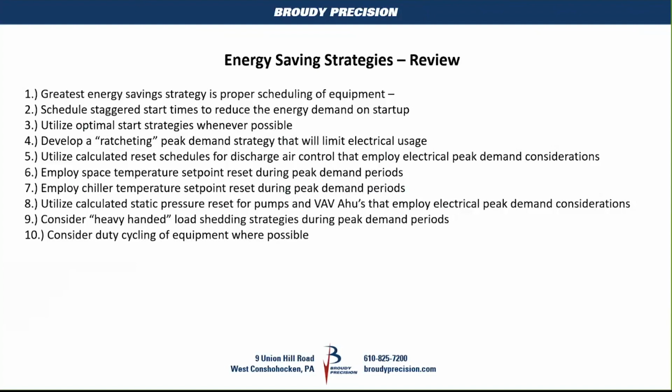We may start it up at 6, but the people don't get there till 8. If I'm only a degree out, optimal start says maybe I start up at 7:35 or 7:45, because I only need 15 minutes to get that 1 degree back when the people get there at 8. That's what optimal start does, and it saves us a little bit of energy there too.